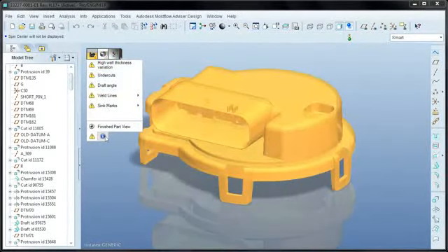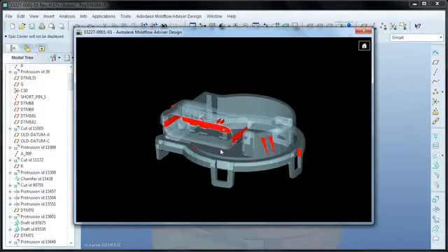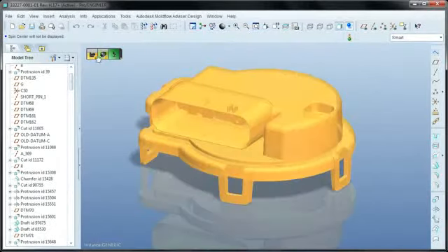The next result for manufacturability checks draft angles. While most design tools already have this ability, the Advisor Design plugin will let you know if you forget to add draft to a surface while you're designing that area of the part, rather than waiting till the end, which may cause rebuild problems later on.